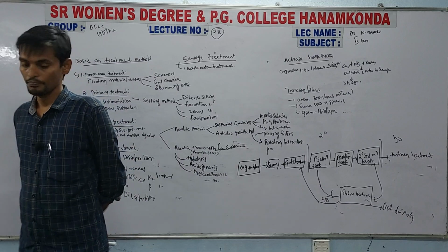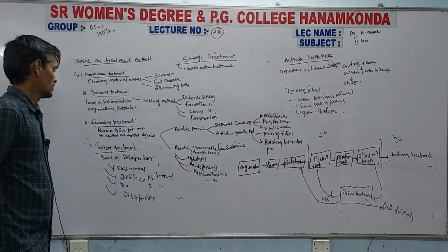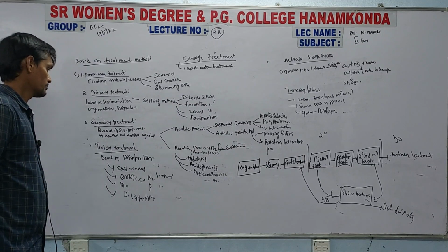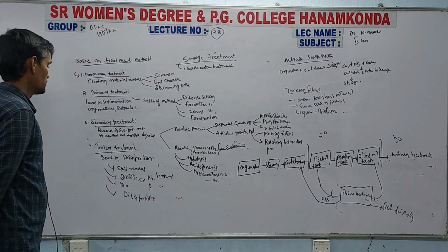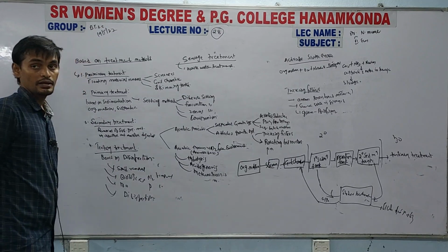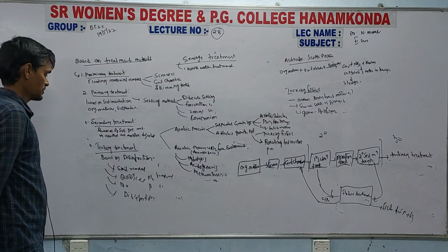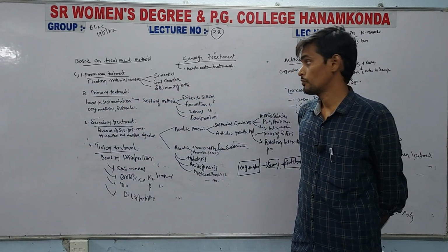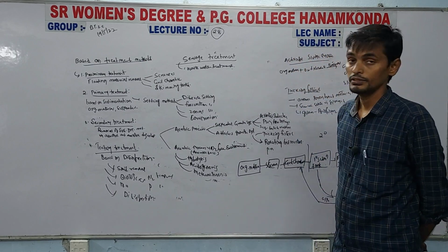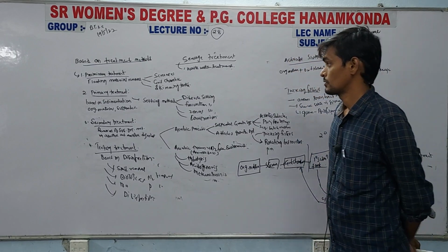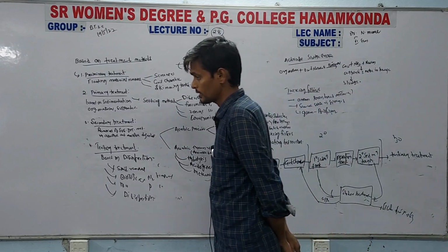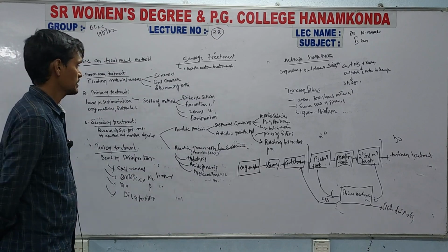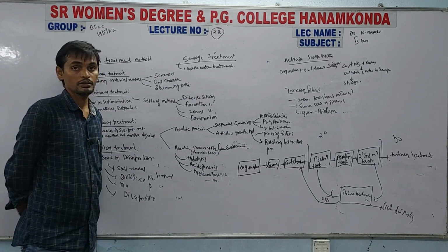Next, secondary treatment, which is removal of suspended organic material by aerobic and anaerobic digestion. Next, coming to the tertiary treatment, which is based upon disinfection. So, these are the 4 methods of how we treat the sewage water. Coming to the preliminary treatment, the floating material can be removed by using screeners, grit chambers and skimming tanks.